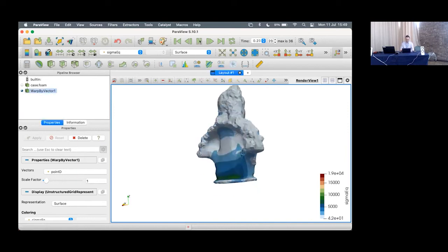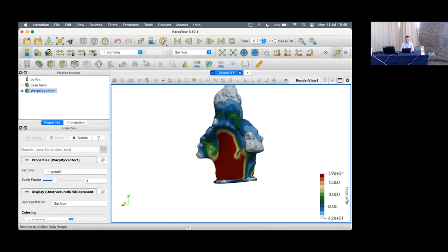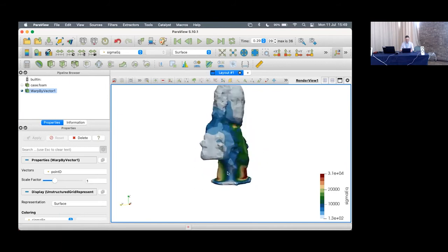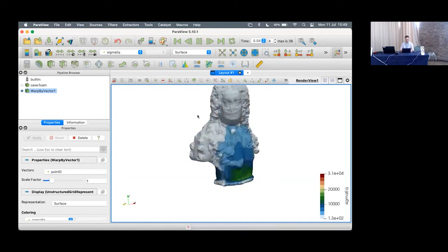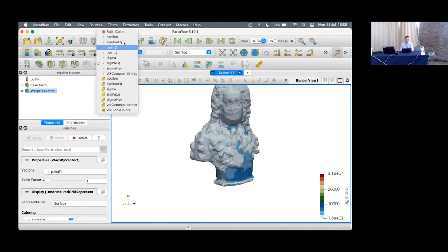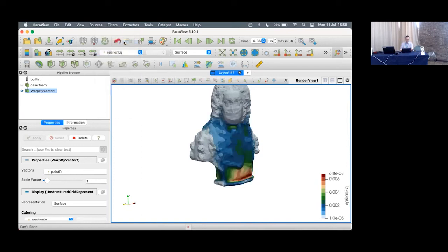In this case, you'll see you get a stress concentration. Let me rescale it again. Just down at the bottom corner, where it's fixed, you get some stress concentrations. And then just under his chin, you get a little stress concentration. So if this is going to crack, in this mode, it would probably crack under his chin or where it's fixed at the bottom. You can also look at strain, which is a measure of the deformation, where the material is being stretched the most.